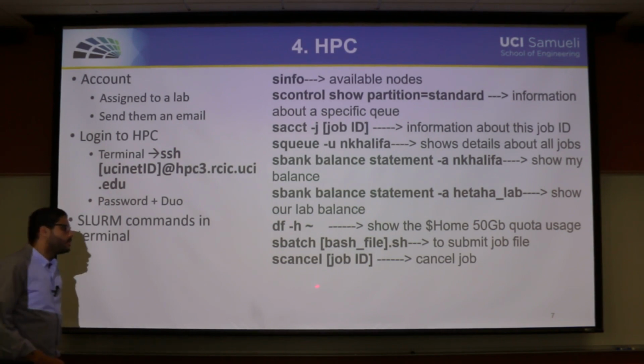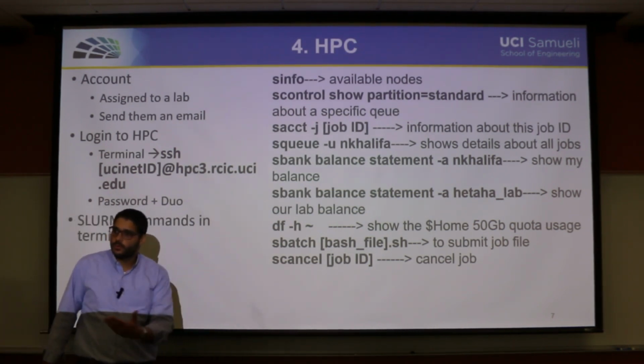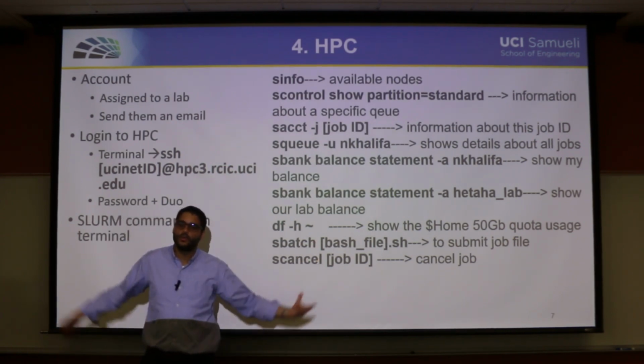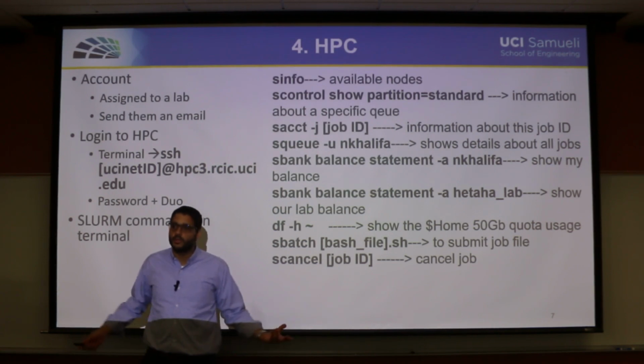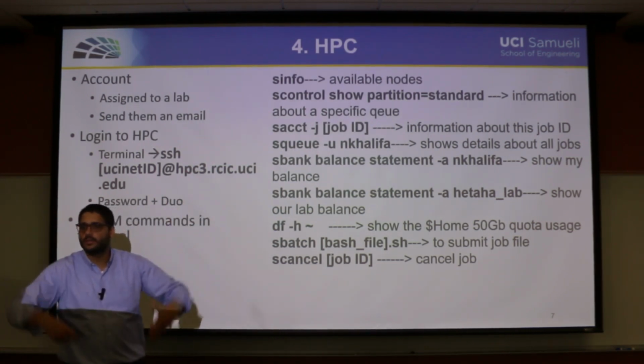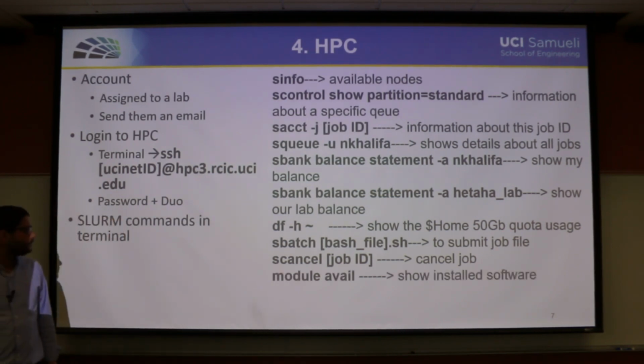Well, let's say, for example, you submitted a job and you'd like to cancel it. You don't want Fluent or whatever your job to keep executing and charging your quota, and you are not going to use this by the end of the day. So you would like to terminate it, force it to cancel. You just use that scancel command and enter the job ID.